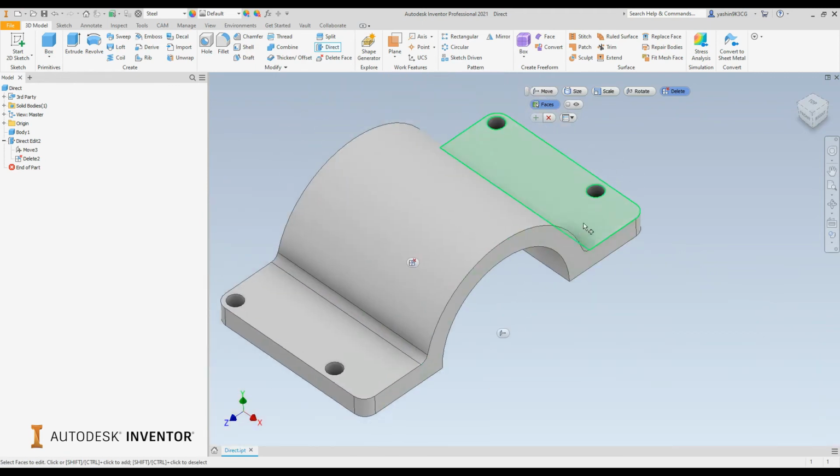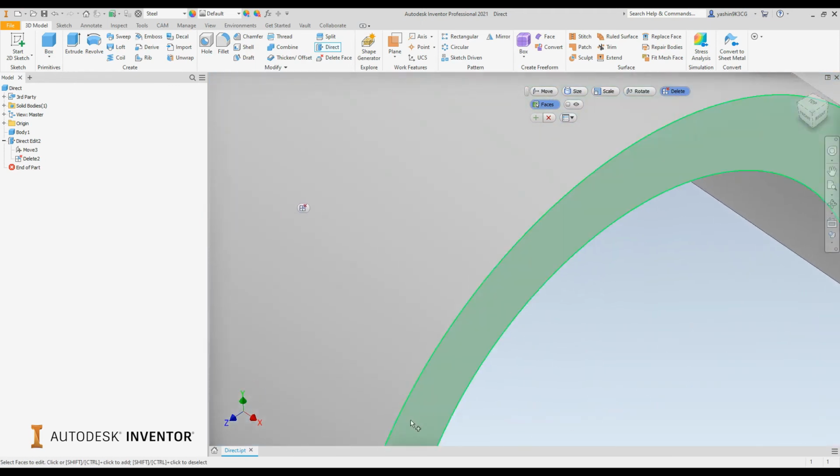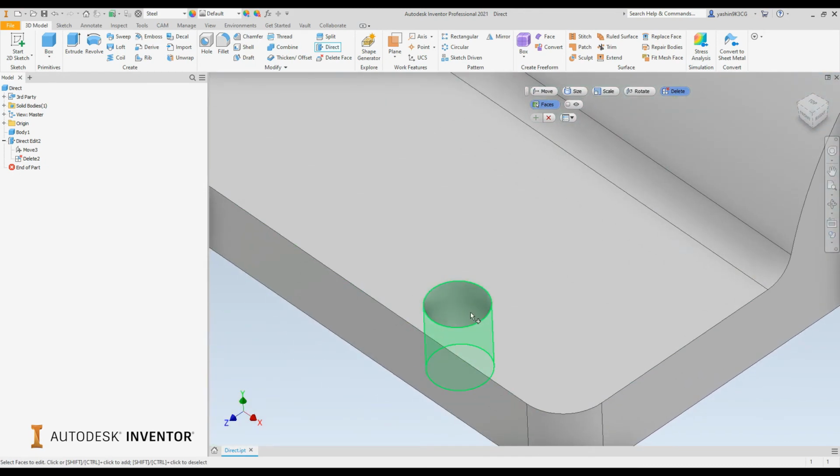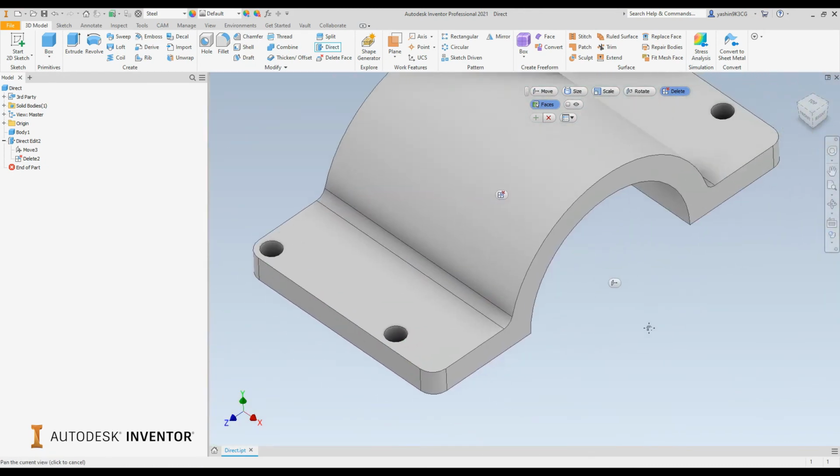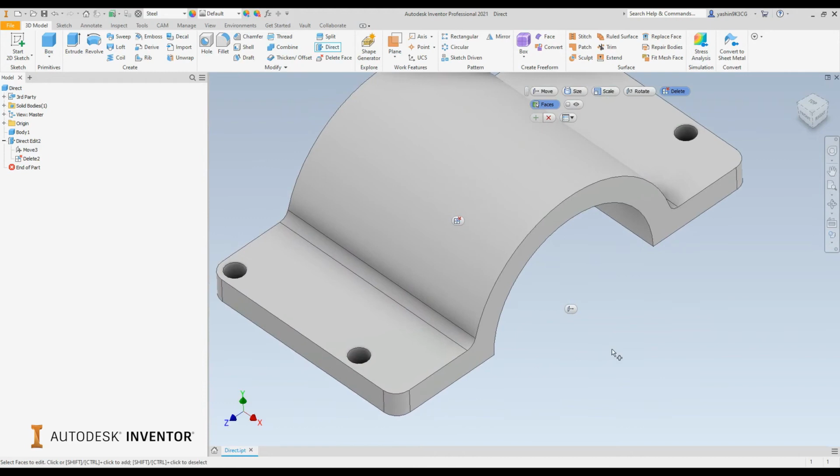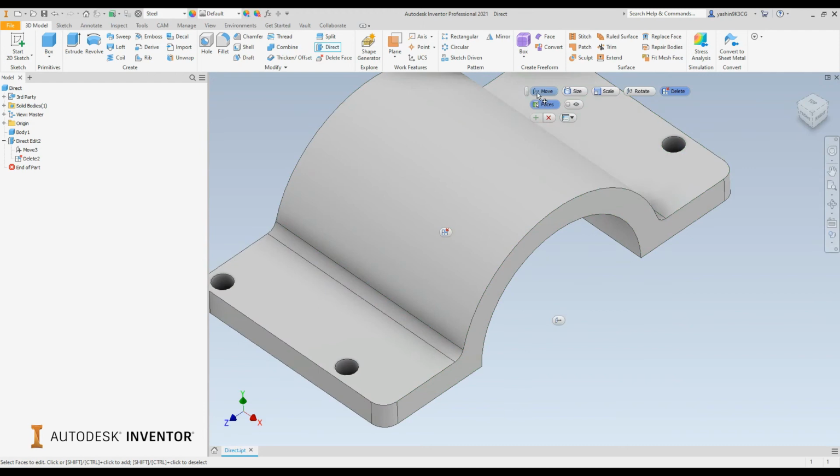Next up, the holes are slightly out of position, particularly the ones where we increased the length of the component, so I'd like to move those over just to align them a little bit better. In order to do that, I once again can use the Move function. Toggle it and select the holes I want to move. I can select more than one at a time.